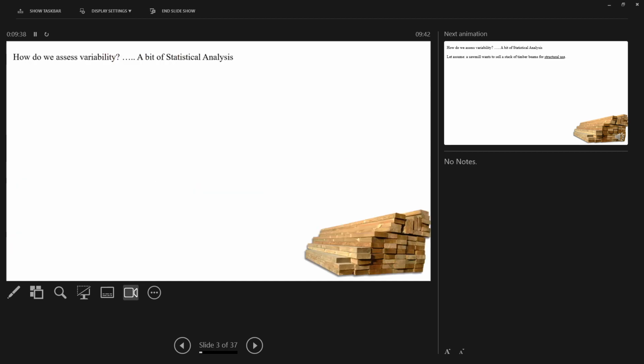Yeah, it shouldn't really be too much of a problem, but we actually want to use Douglas fir for other reasons. Douglas fir is very good for weathering, so it won't rot as fast as say Sitka or other materials. Larch is another material we could have used, which will last outdoors. However, we want to know the material properties not just of the average Douglas fir, we want to know the material properties of the Douglas fir from this particular plantation, which is quite a thing.